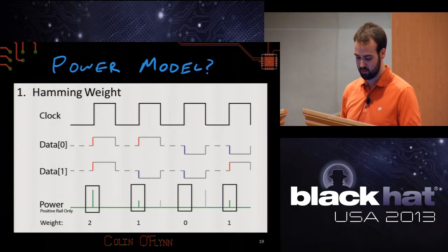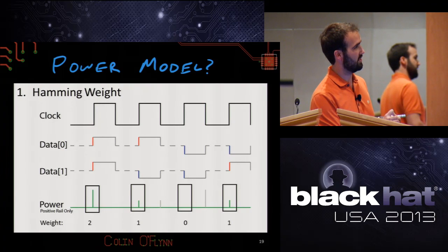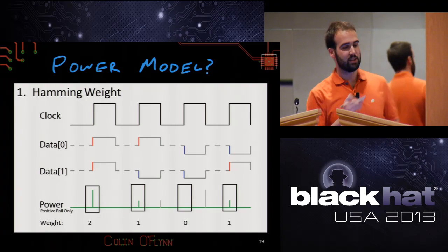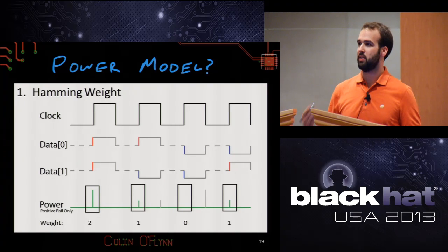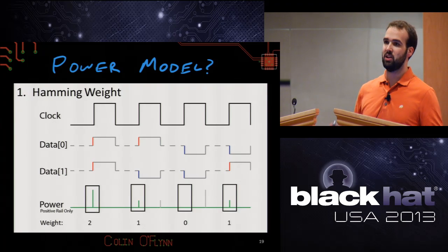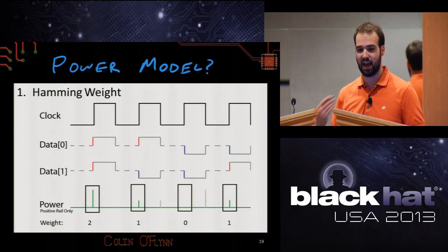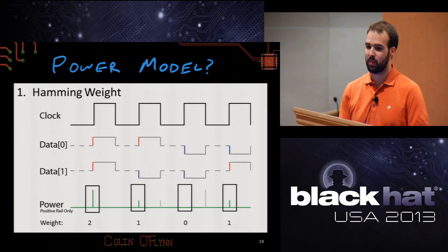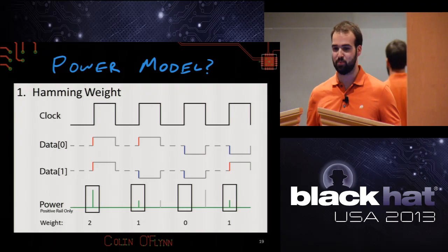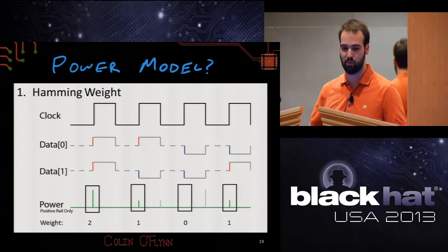So instead what they do is they always switch the data lines to a pre-charged state, which is effectively this intermediate middle state here in dashed lines. This pre-charged state is halfway between the 1 and the 0. The point being that when you want to switch the data lines to the 1 state, you no longer go from 0 to 1 potentially. You always go halfway to 1. So it's half the required power. So your worst case scenario is now much better than when you're switching all the lines from completely to 0 to completely to 1.